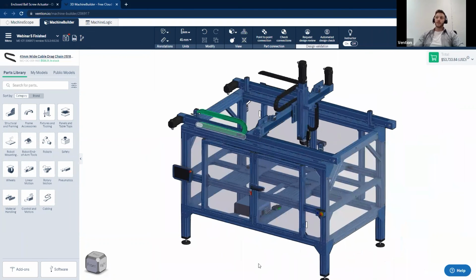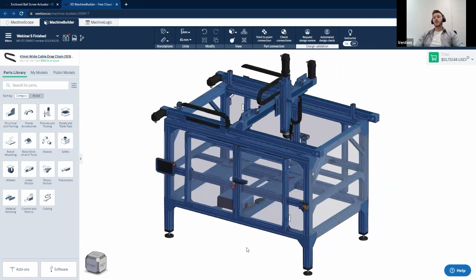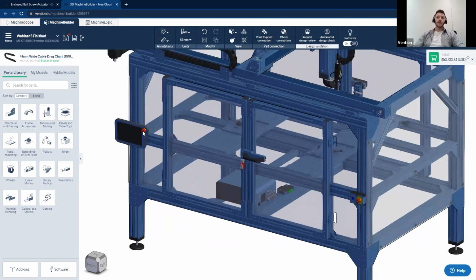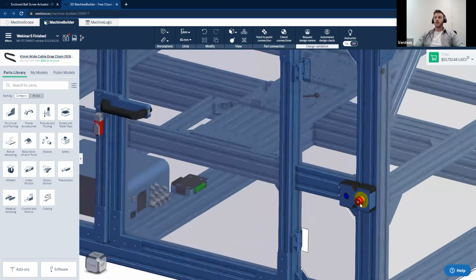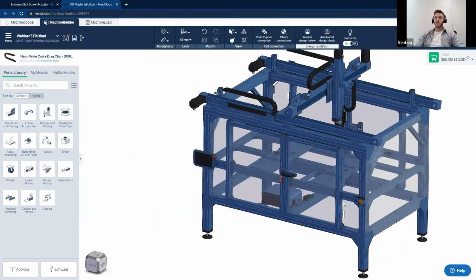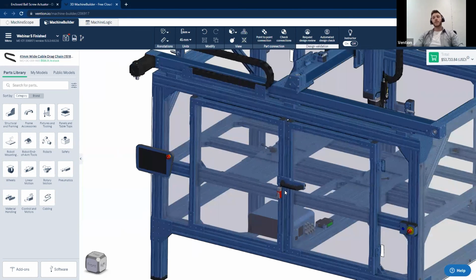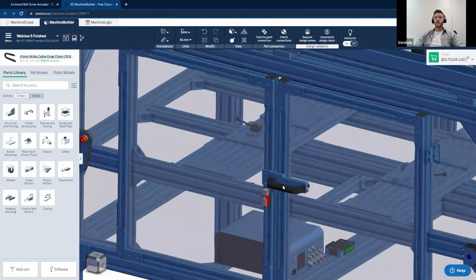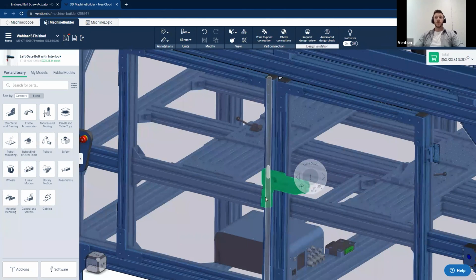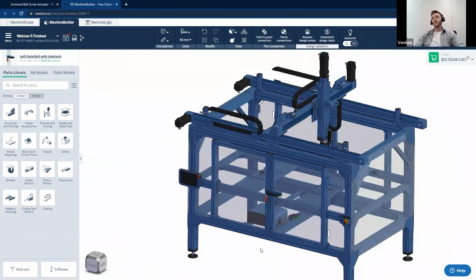One of the final things that should be considered when designing a gantry robot is safety. For safety systems, Vention is also able to supply these as well. You have e-stops on the pendants themselves, and e-stop and reset modules that can be located at any point along the structure. Say you are opting for a door type enclosure, we have gate bolts with safety interlocks. If you're looking for a little bit more ease of access, we also supply light curtains and laser area scanners.